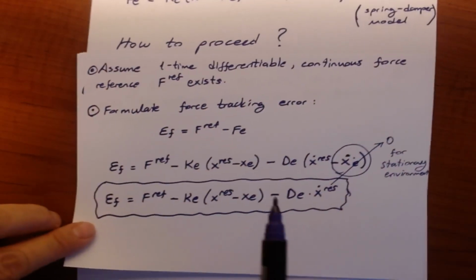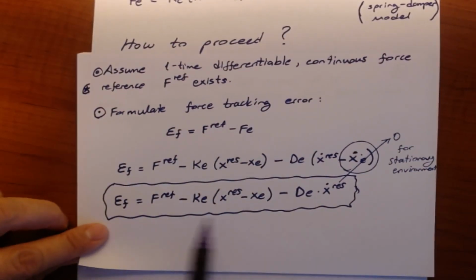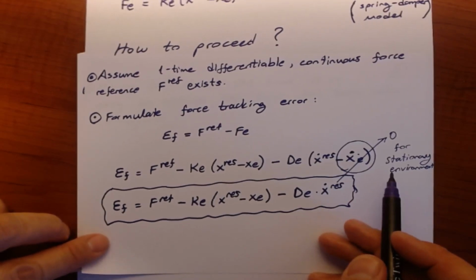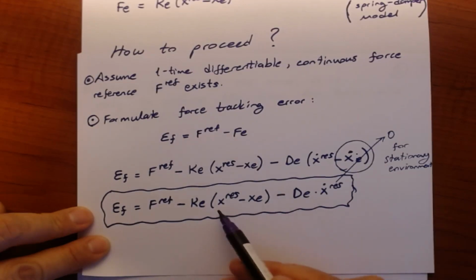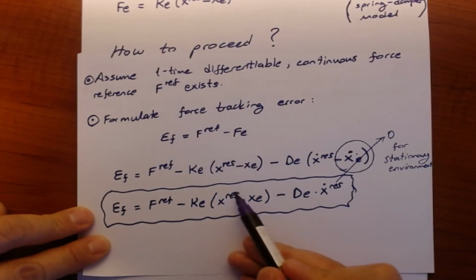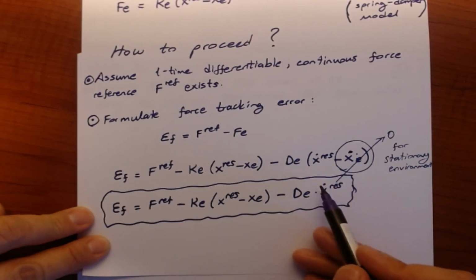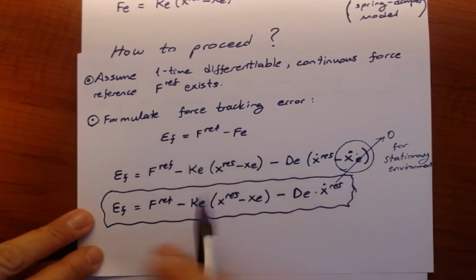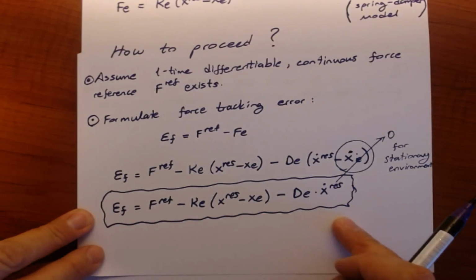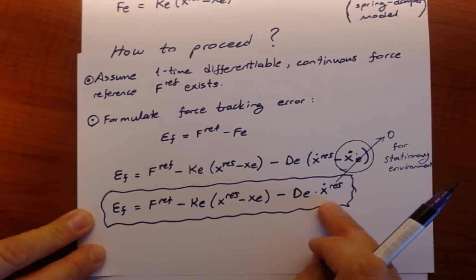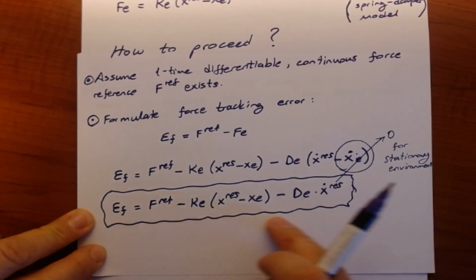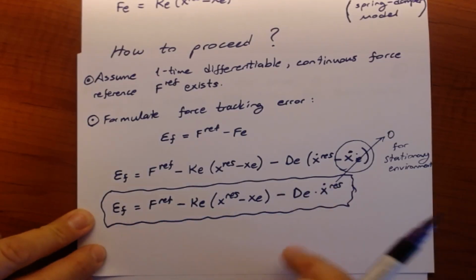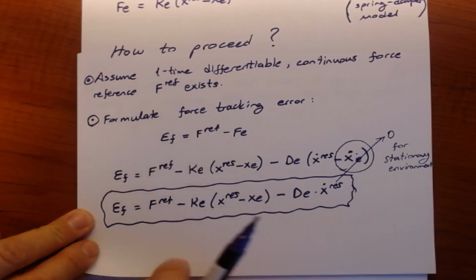So if you look at this, what kind of approach we have to pick up depends on the structure. Now in the error, we have the response position of the system and response velocity of the system. And don't forget that while trying to enforce certain dynamics, we were trying to extract the response acceleration and give this to our plant as the desired acceleration, as what we have already done in simple velocity control, position control, or generalized error control applications.